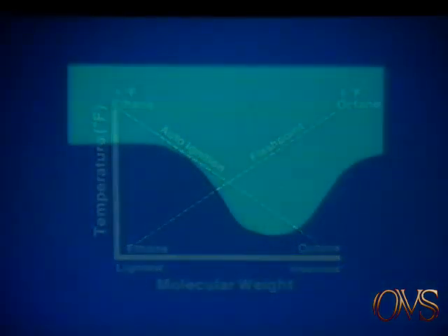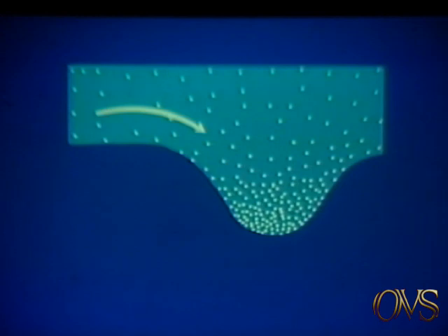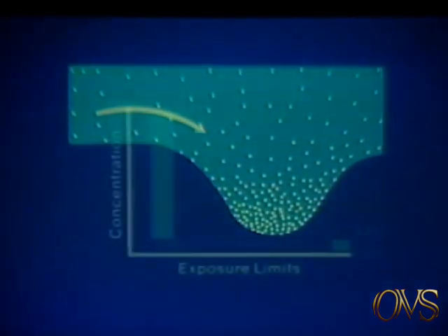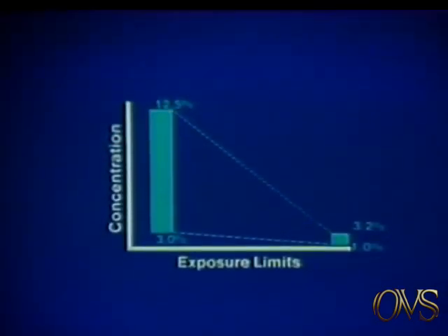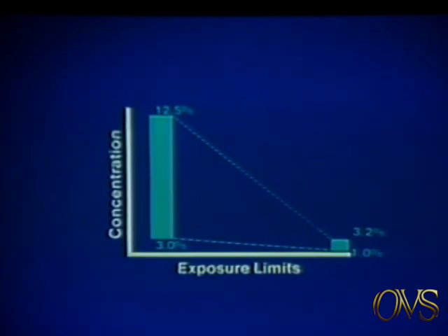The vapors from NGL components will seek depressions and low-lying areas, since they are all heavier than air. These NGL vapors may also form a visible cloud when in high concentration, although in general the gaseous hydrocarbons are colorless and the liquids are water clear. Flammability ranges for NGL vapors go from 3% to 12.5% for ethane, to a range of 1% to 3.2% for octane. However, since ethane may be undetectable by smell within its explosive range, a combustible gas test is the safest course.